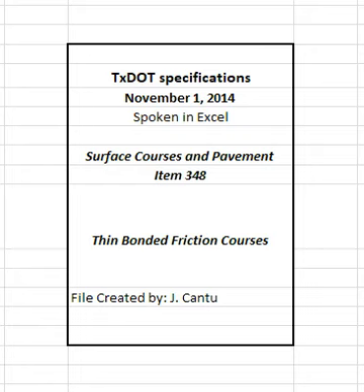4.4.2.1 Contractor's Responsibilities. 4.4.2.1.1 Super Pave Gyratory Compactor. Furnish an SGC calibrated in accordance with TxDOT for molding production samples. Locate the SGC at the engineer's field laboratory and make the SGC available to the engineer for use in molding production samples. 4.4.2.1.2 Gyratory Compactor Correlation Factors. Use TxDOT Part 2 to perform a gyratory compactor correlation when the engineer uses a different SGC. Apply the correlation factor to all subsequent production test results.